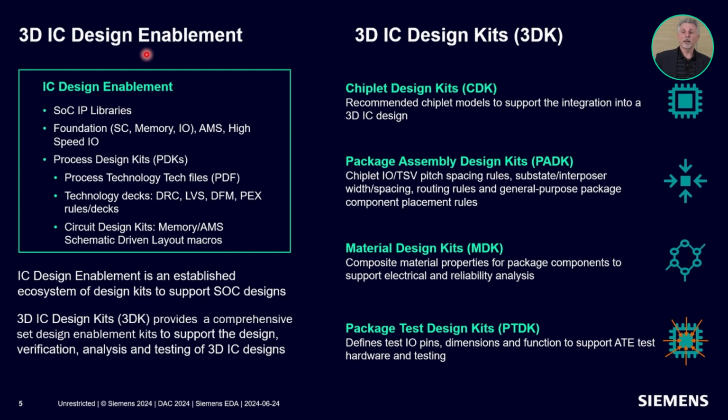Another area is material design kits, and this really is a novel idea. When you're doing the analysis, whether it be thermal, stress analysis, signal integrity, or power integrity analysis, you do need to define the material properties of the components inside the package. And again, rather than having that information derived ad hoc from the vendors, the material providers and such, and then manually put into the tools, the idea is to put that in a machine readable format. We call it a material design kit, or an MDK. And then the tools would take that material information directly for doing the analysis.